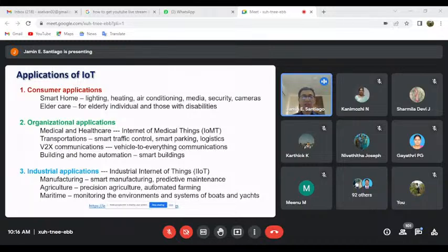So to avoid this, we do predictive maintenance based on IoT devices so that we can take this machine out of production during times which are convenient, for example, during weekends or downtimes. So we can get this machine out of the production line and repair it, without affecting the production and the safety of the workers, and of course prolonging the lifespan of the device.